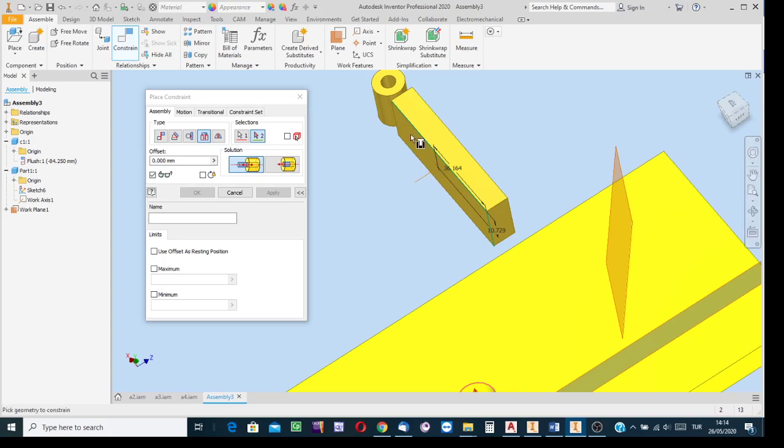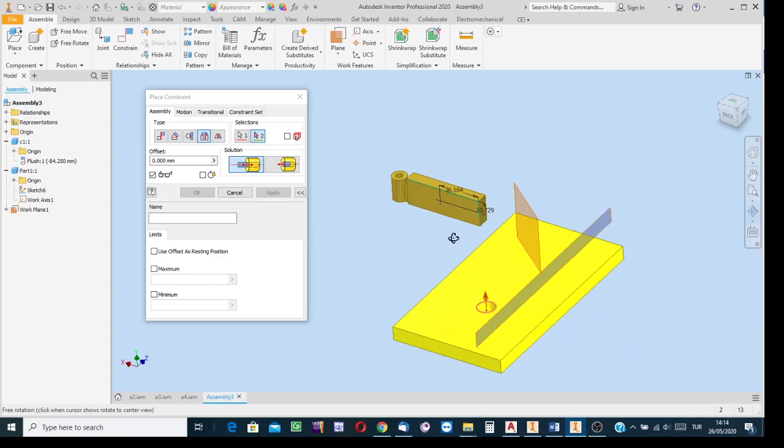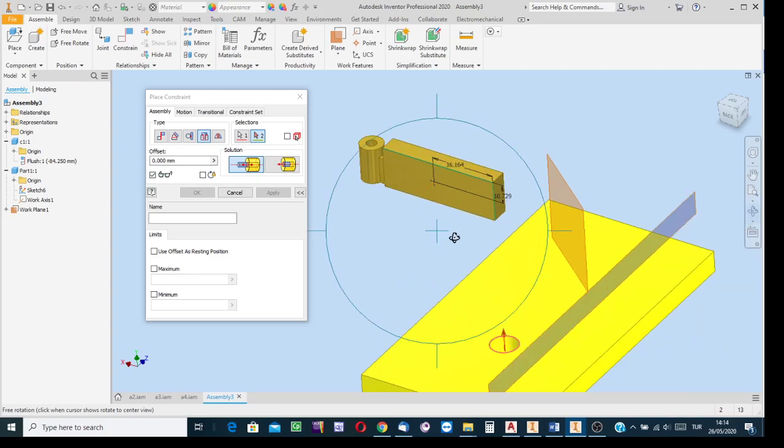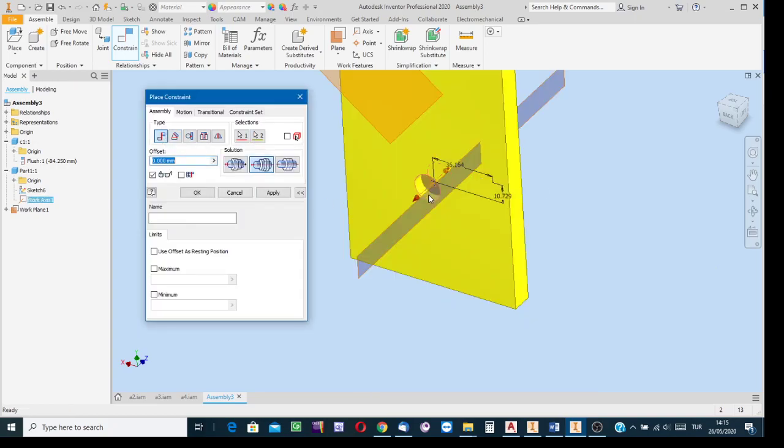Normally a longitudinal axis is defined for holes and revolved bodies, but for rectangular prismatic and trapezoidal prismatic parts the axis is not defined, so you need to use a work axis. Whenever you use a work axis, since it is not a longitudinal axis, positioning it with respect to the other using insertion type constraint is not possible. It is a trick really. Select this type, not insert, but as-if flat surface mating. And then indicate this axis. Yes, now it can be indicated.